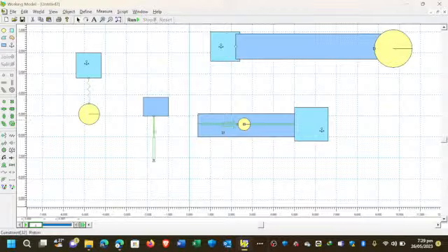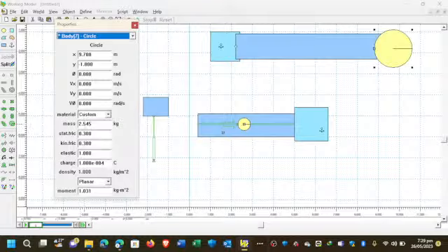Well, that is it for actuators. What it means is that if you double click on this circle now, you could change the mass of the circle. It's taking it as a body. You could change the static friction, kinetic friction, elasticity, the material. You could even change the material: steel, ice, wood, plastic, clay, rubber, rock. You could change a lot of things. So this is a very, very powerful tool. And the setup I sent to you.